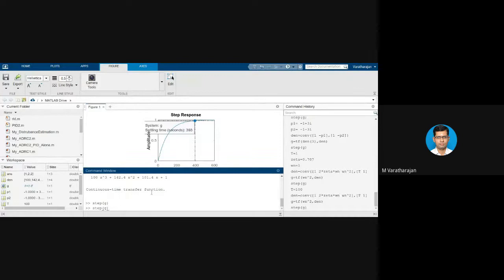Now let us put T a different value. T I am putting at 0.01. That means this particular pole will have its effect only for around 4 times 0.01, that is 0.04 seconds. After that, it will die out. Okay. It is a very fast pole.